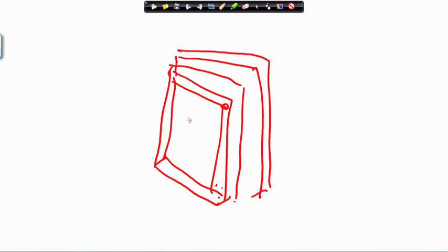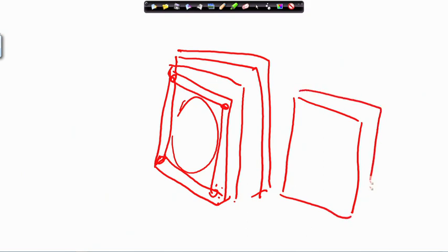So, in between the frames, here this is hollow, am I right? Now, we put some kind of thick cotton pad in between the frames, and since it is made of wood, we can make a hole in it, and through this hole we can put some kind of nut and bolt arrangement, so that we can fix that. So, suppose this is a frame, and here there is another frame, and another frame like this, multiple frames we can bunch all together like this, and in between we put one cotton pad inside, and then we pass the liquid in between this cotton pad.